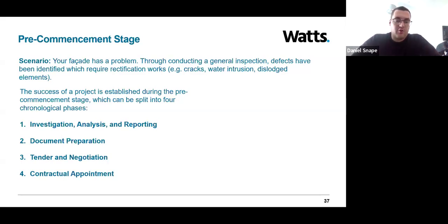So standard forms of contract without amendments are typically preferable, but in practice this is rare. Often you get bespoke forms of contract or long and often complicated schedules of amendments or schedules of derogations that are there to try and reduce people's liabilities, in which case having a legal advisor to look over those is always important. So yeah, it is generally very important that your professional team and legal team review any of these schedules or lists of clarifications and derogations to ensure that you're not left open to the risks or any sort of key exclusions.